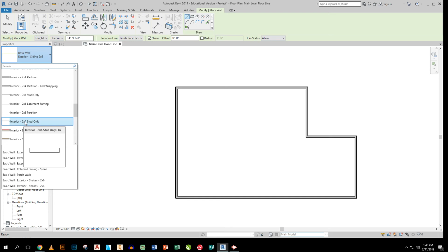Now, this comes down to how you prefer to draw your plans. In my brain, it works this way. The drywall contractors are going to put drywall on all of the studs that are there. The people that need to know the dimensions are the framers. Now, in my brain, how that works out is this: I draw usually to bare stud. But because I didn't start drawing that way today, I'm not going to continue that way. So I'm going to actually use a 2x6 interior partition.